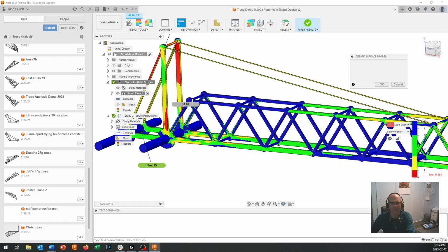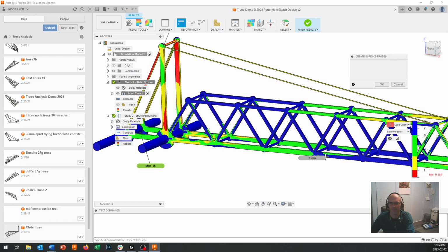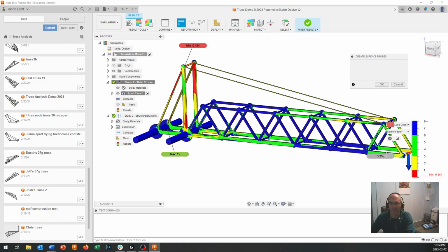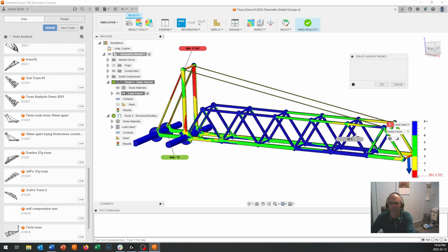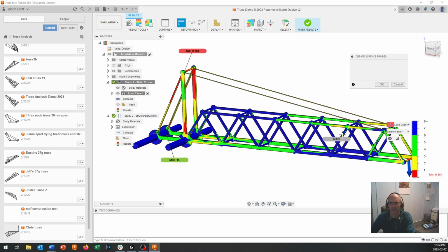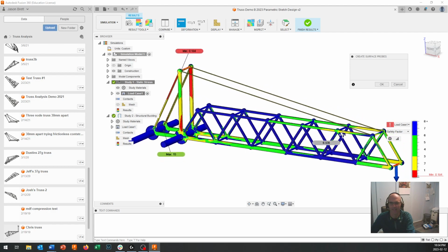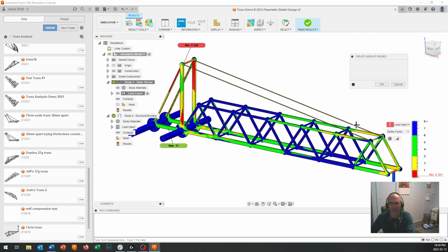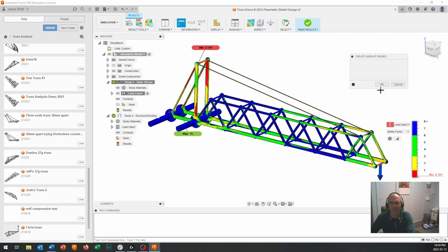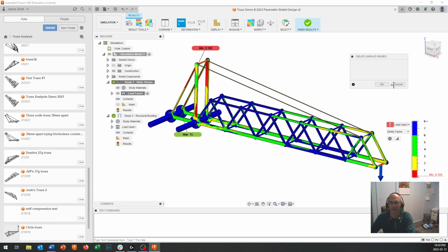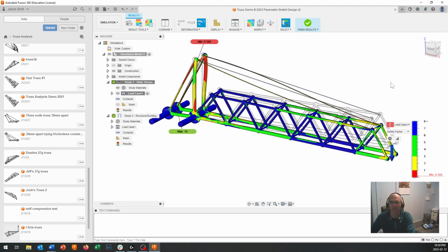But up here, safety factors of 14, 15, 3, 5, that's really sturdy and quite a bit overbuilt in some of these sections right out here. I should be able to come along and, based on just the static stress, reduce the size there, get that weight down, and maybe get the score up and have a chance of a design like this actually working.